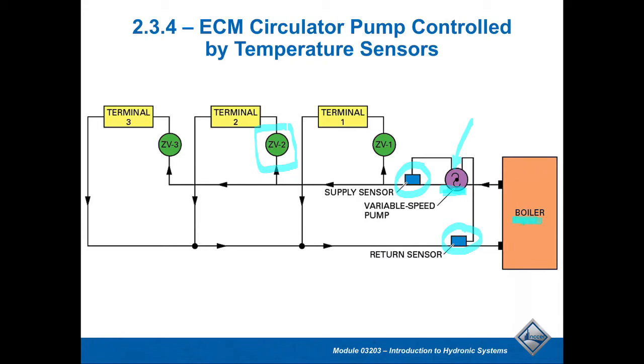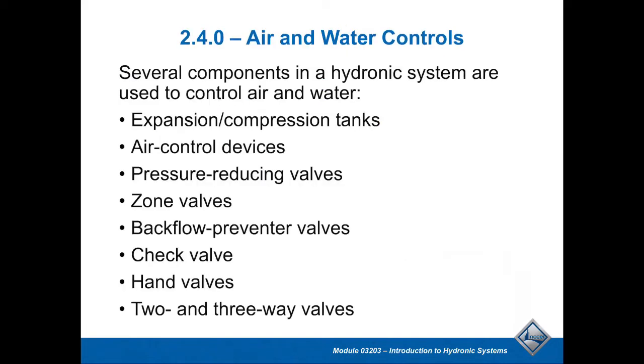So depending on the system you have and the complexity of the boiler system, you may have a system where you could have a variable pump and you could have a modulating boiler or a multi-stage boiler that could very efficiently control the system to give you the proper amount of water flow. They're really outstanding. They do just a fantastic job. I've seen some of these applications where they're running both. You can maintain constant pressure for a zone system. That would be the best scenario. Or you can look at it from a standpoint of variable speed. There's a number of different ways to do it. But it's the current technology that they have right now.